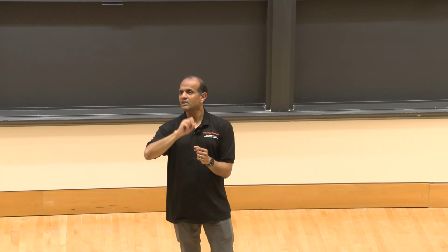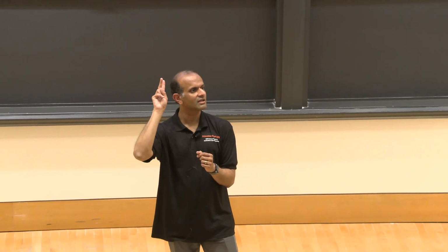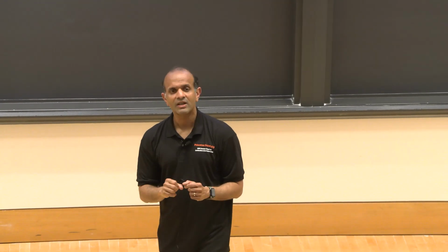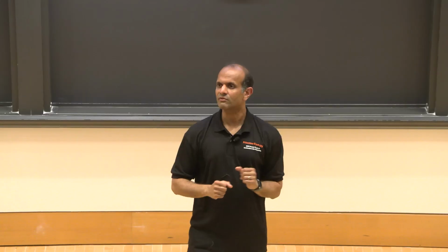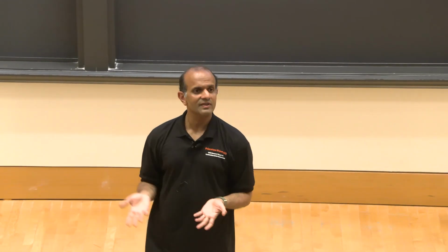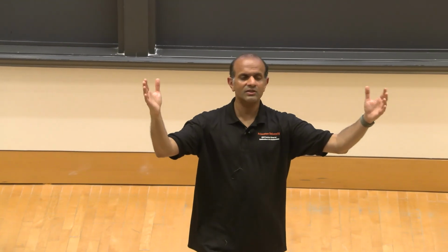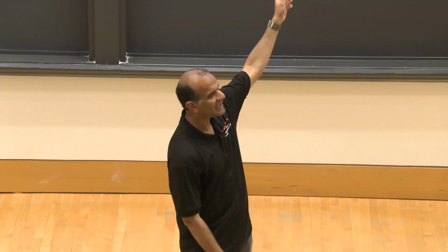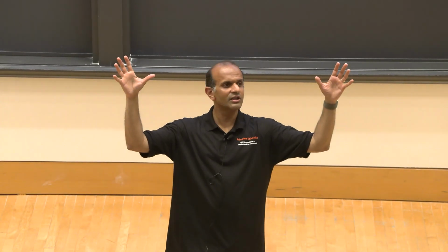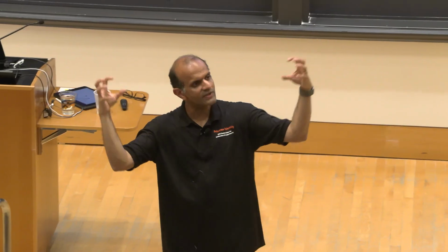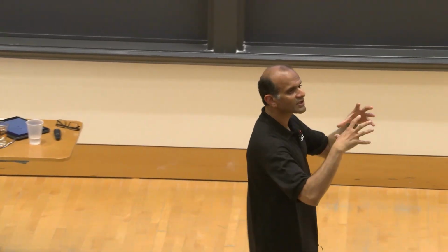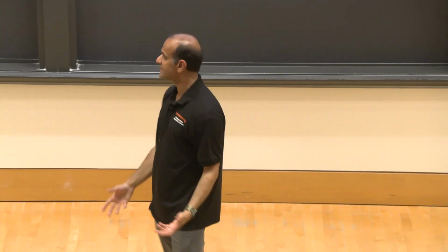If you use flamelet models, mixture fraction and dissipation, there are 2 variables. But that's only for the flamelet part of it. It's not for the CFD part of it. But you can think of it the same way. You have 30 species, you have reduced it to 2 variables. You have 10^12 variables, you can reduce it to a much smaller dimension because thermodynamics forces everything to live in this much smaller volume, okay, in this space.